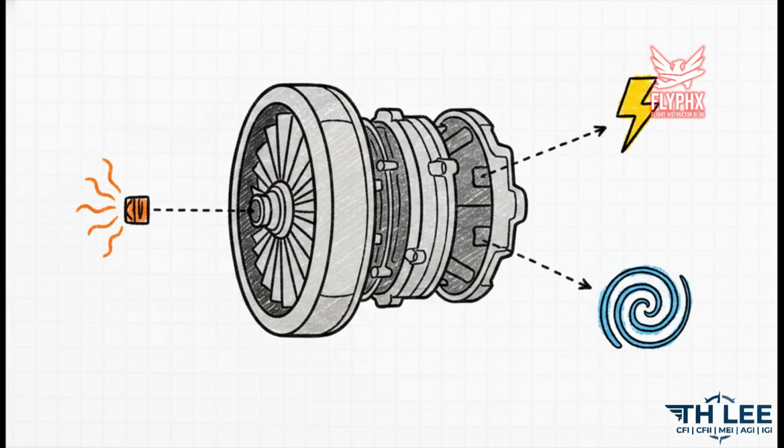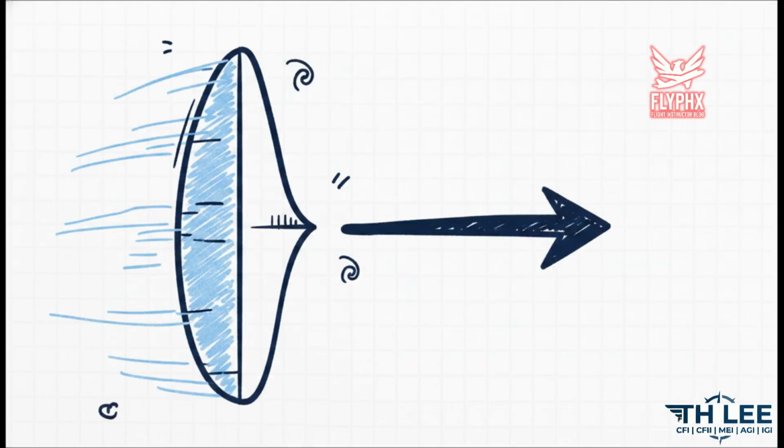And here's the thing, that heavy engine isn't just sitting there to spin the propeller. It is literally the beating heart of your aircraft's survival systems. It generates the electrical power needed to run your avionics. It spins a pump to provide a critical vacuum source for your gyroscopic flight instruments. And in most single-engine airplanes, it provides the absolute vital source of cabin heat that keeps you alive in freezing temperatures at high altitudes. And bolted to the front of that engine is, of course, the propeller.